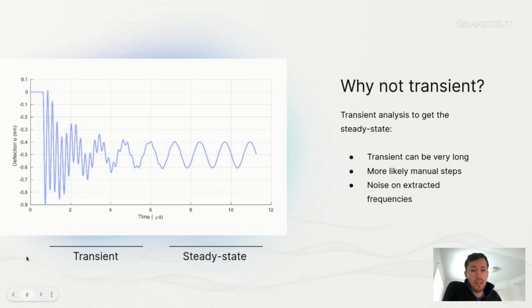The downside of doing this transient analysis is that typically for these MEMS ultrasound sensors, for example, the goal is that they have a really high Q factor in some cases. And so this transient here is actually very optimistically short, but there are many applications where the transient takes forever. You have thousands or tens of thousands of periods before you reach the steady state. This is where it's absolutely impractical to do a transient analysis. You really want to do a nonlinear frequency analysis, which is the harmonic balance method.